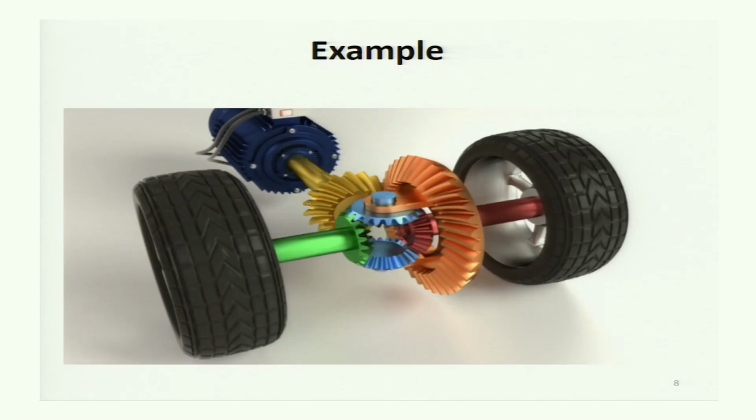The differential is shown again. The motor is given, and the propeller shaft is getting power from this motor. This is the shaft axis, and the axis in which you want driven power is this one. So the angle between the shafts is 90 degrees, and which is achieved with the help of the bevel gear sets.